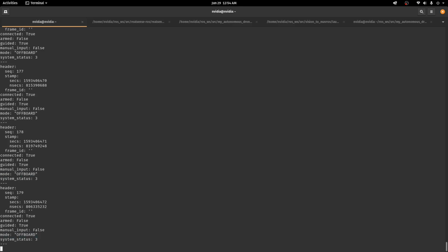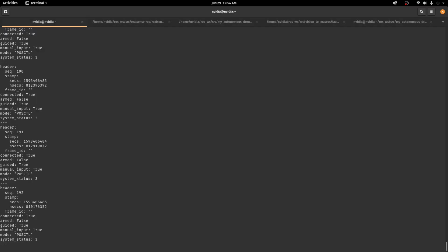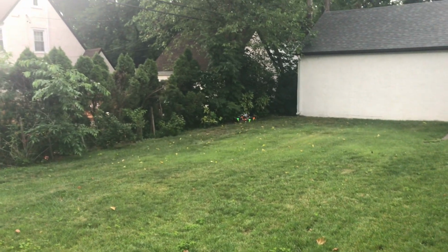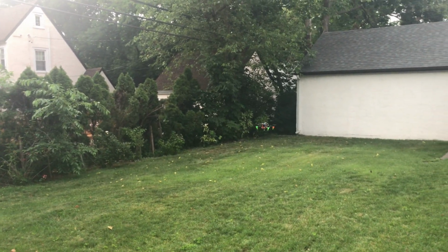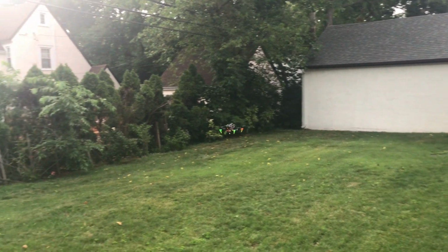When you switch off off-board mode, Mavros will go back to the last mode you had. By doing this, you avoid having to take over control immediately, which is impossible and leads to a crash. For landing, you would then gradually go to manual mode. Thus, our DIY autonomous drone project comes to an end. I hope this tutorial series will get you up to basics so you can make more intricate and useful drone projects.